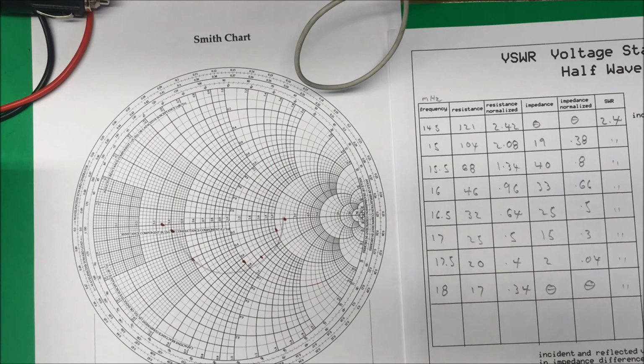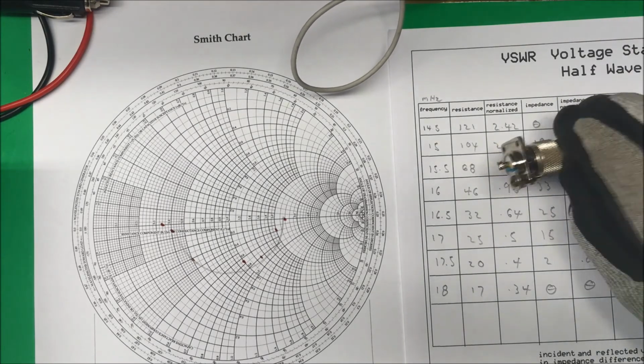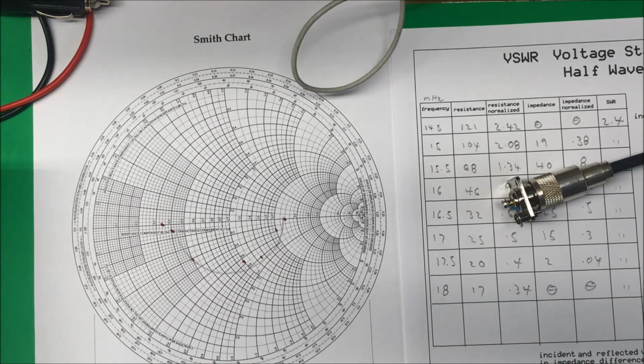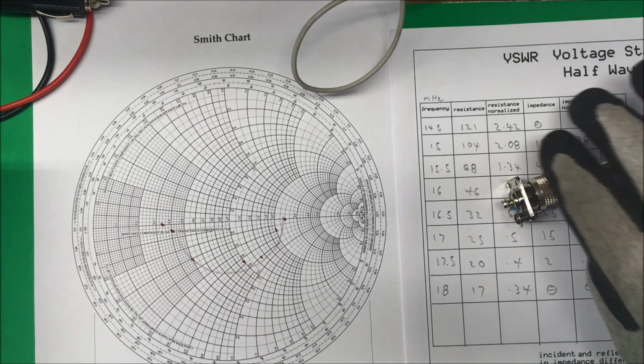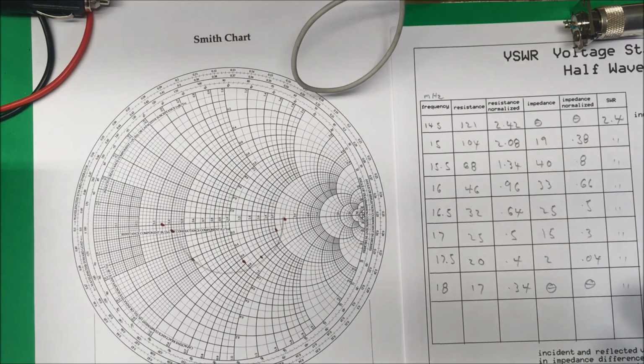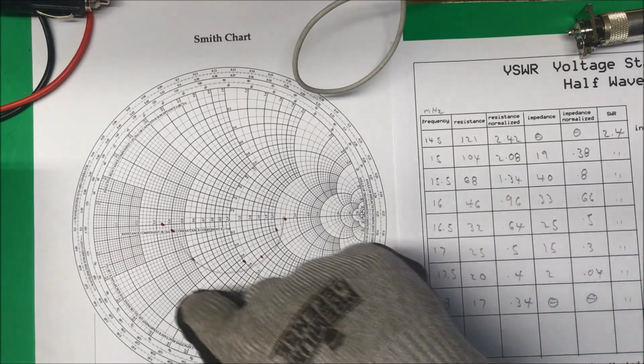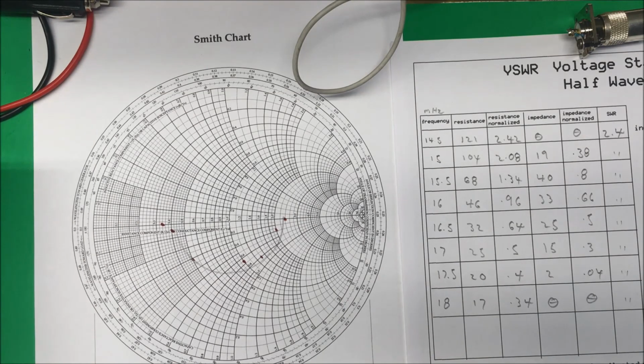I could probably use a better meter. Now the trouble with this resistance is some resistors are frequency dependent. This happens to be a metal film resistor. There's metal wound around and coiled around there, and it might have some inductance in there. And even carbon resistors can have some capacitance or change with frequency. So that could be part of the problem here. But anyway, that's the half wavelength cycle on a Smith chart, and halfway around the circle is 1/2 wavelength.